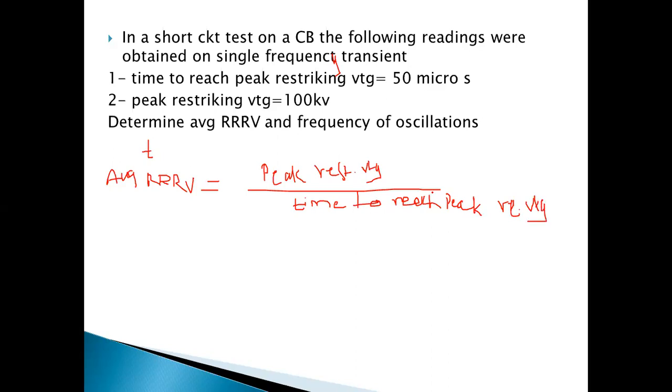It is already given: the peak striking voltage is 100 kV, and the time is 50 microseconds. So the answer is simply 2 kilovolt per microsecond.